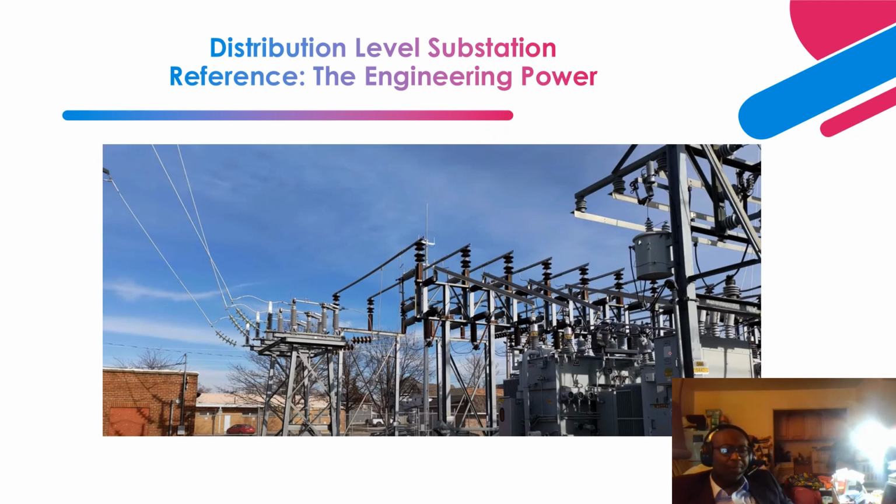This is another picture from a different angle. It shows the incomer going through disconnect switches and through the tubular bus arrangement. These are all support insulators, and like I indicated, the support insulators provide a ground plane protection for the live conductor. I showed you that these are porcelain type bushings, and the number of them is based on the voltage level.